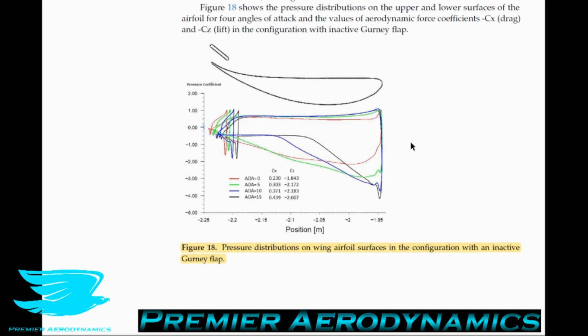If we're going around corners, then that might be acceptable because the increase in downforce is good to get around the corners, and the increase in drag also helps us decelerate. As we go to high angles of attack, the drag skyrockets. It goes up to like double, and the lift coefficient doesn't really change very much, if anything. So we're getting a lot more drag, which will help with braking, but we don't really get any more downforce, which won't really help the car go around the corners much faster. Also, if we are going slower, we lose lift or downforce as well, because downforce is proportional to the velocity squared. So that's also a potential problem there.